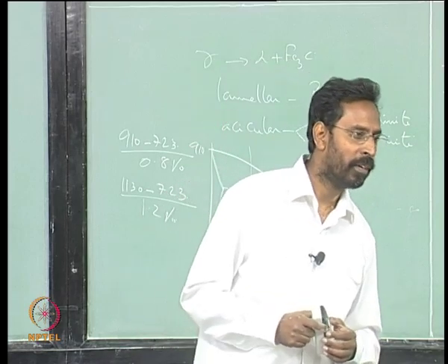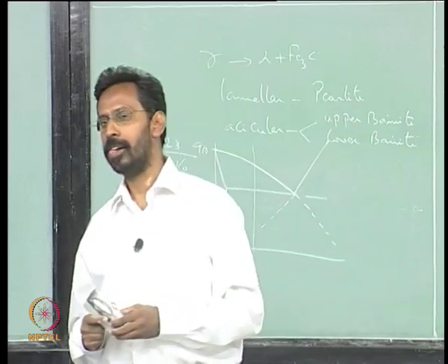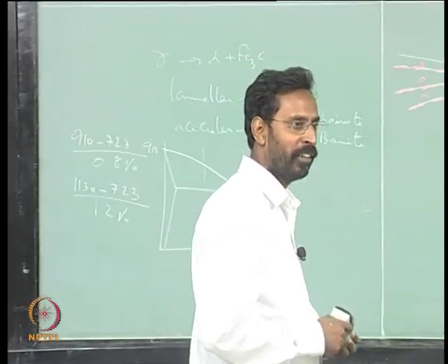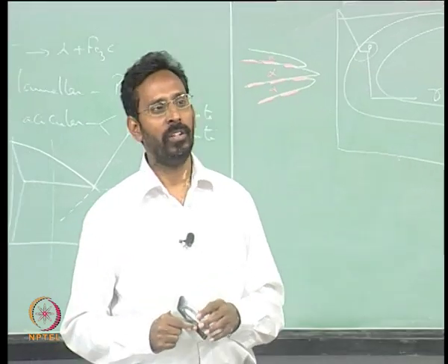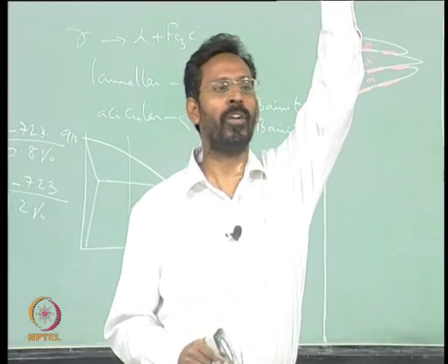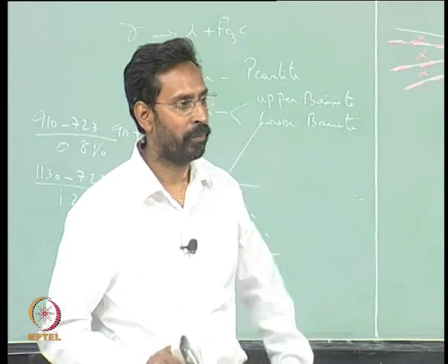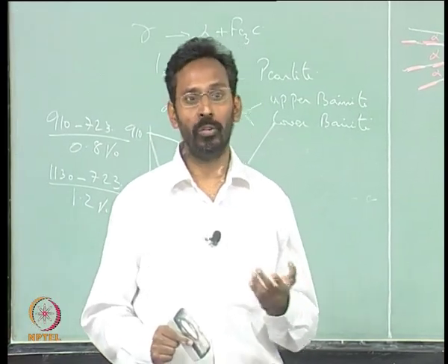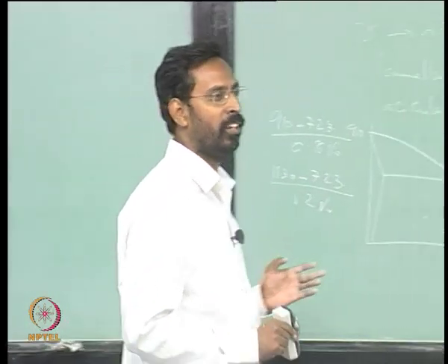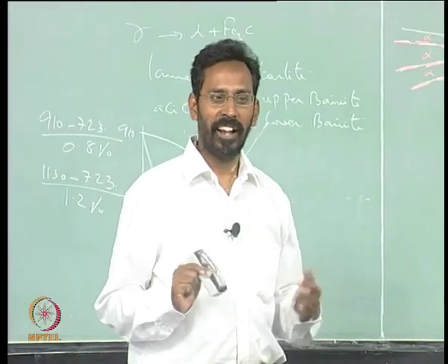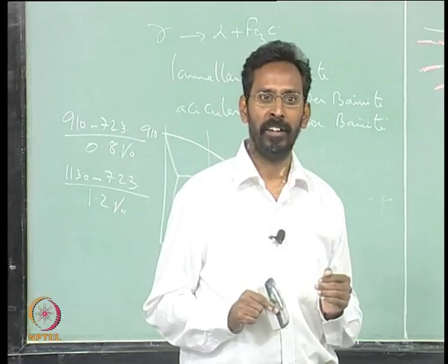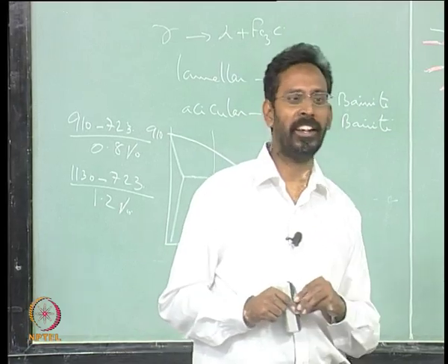but still there is a problem, strength decreases, okay, coarse grained strength decreases, fine, toughness decreases, okay. One more, you get more quench cracks when you are quenching to get martensite, because you are quenching from a higher temperature, thermal shocks are more, so that is the reason why. So with tool steels there is a possibility of quench cracks, that is the reason why tool steels you do not quench them. Luckily because the carbon is higher, the hardenability is higher already. Why is hardenability higher if the carbon is higher?